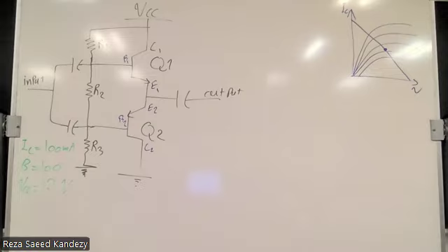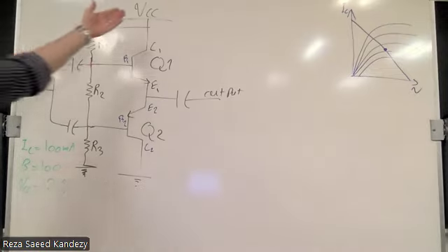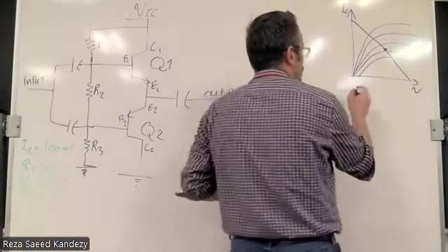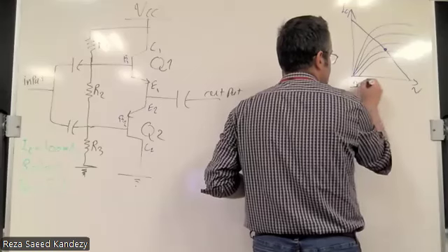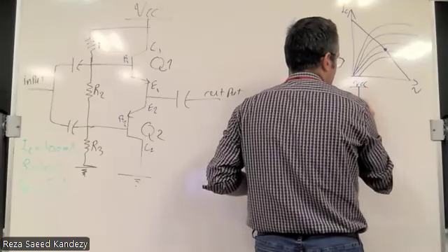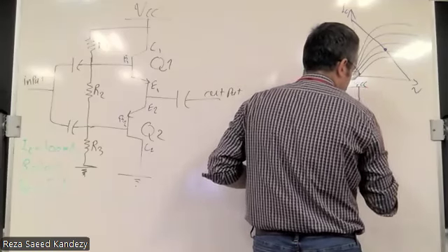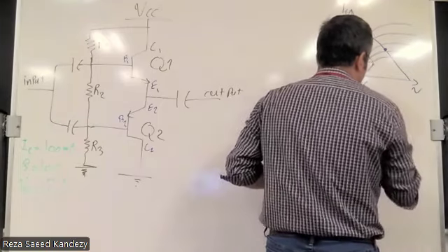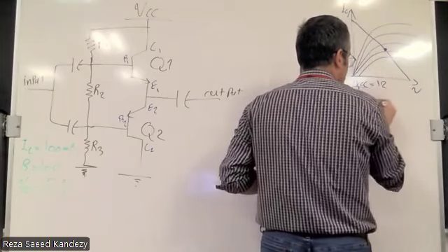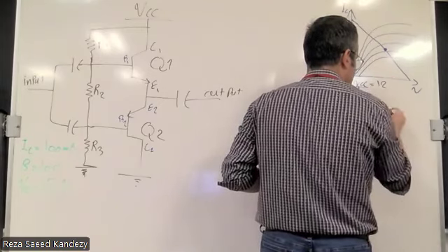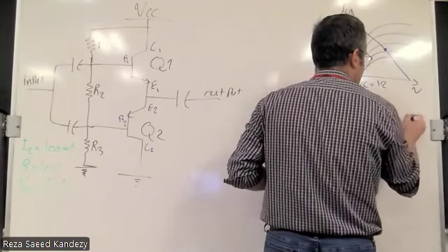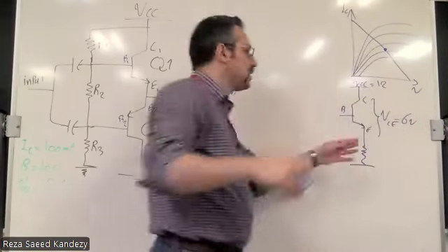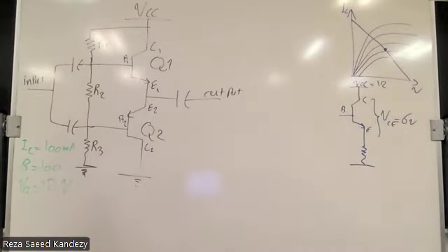So for example, if we had the VCC and one BJT, with emitter, collector, and base, and this was 12 volts, we wanted this voltage VCE to become 6 volts. Now we design the rest of it to gain that voltage based on the collector current that we have.